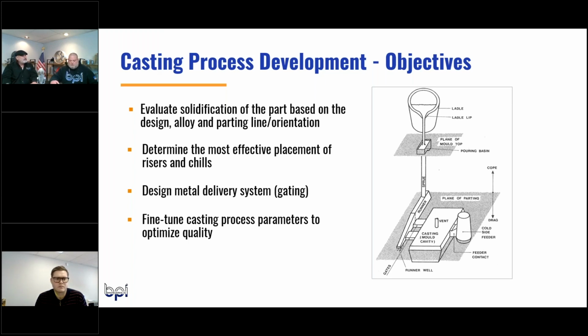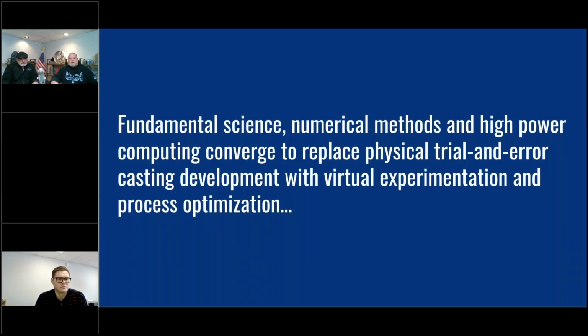not removing metal or welding it back up and things like that. One of the things that I wanted to point out with Vadim is that very first bullet point of the casting design. I think in every webinar we've talked in some portion about casting design and how important that is up front. A lot of people need to understand what is required to make a casting: the drafts, the wall thicknesses, thick sections inside of thin sections, all those important things. Once we get that driven, the other ones can fall in place. But I really think that's one of the bigger topics, that first one.